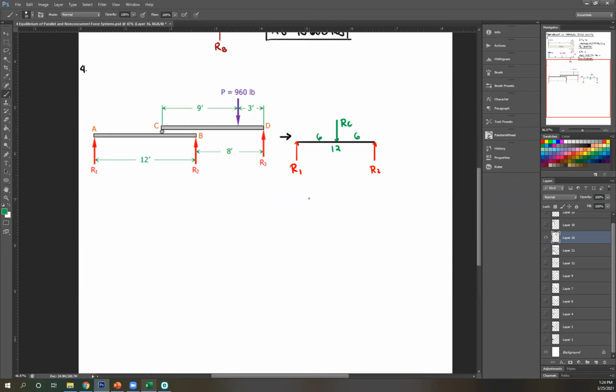Also, another thing to note, looking at this drawing, if I want R1 and R2 to be equal to each other, the forces should be symmetrical. So that left side is equal to the right side. That's another way to look at this. So let's say I have 3 forces. They have to be symmetrical. That's one requirement, so that R1 equals R2. Because for symmetrical systems, left side equals right side. So that's one problem down.